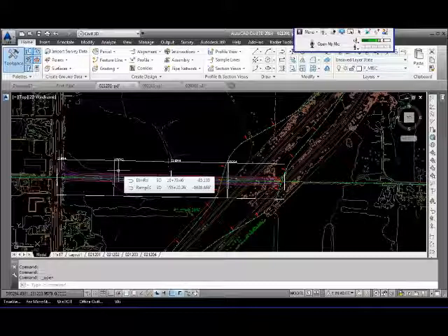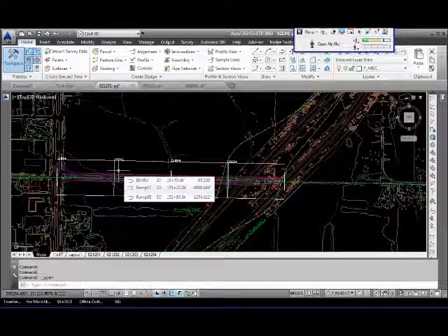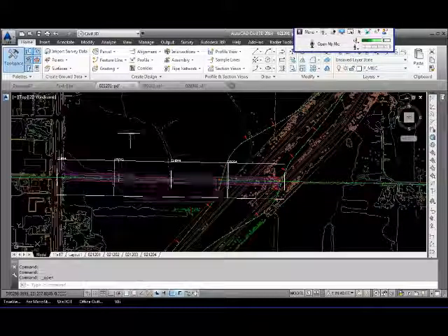Well, you can do things to help yourself with that load time and the speed of flipping between model space and paper space. A lot of people come to me and say, it takes forever for me to switch between tabs. Obviously some things you can't change about how your drawings are set up, but there are at least a few little things that may help you.